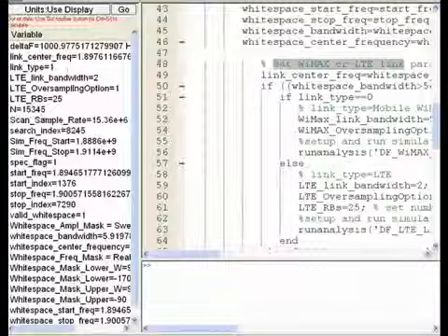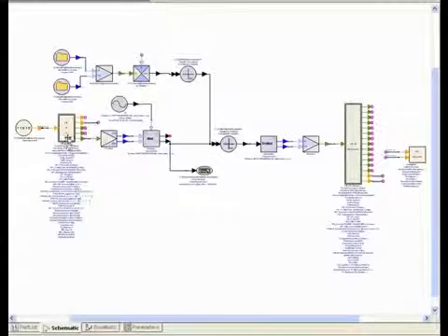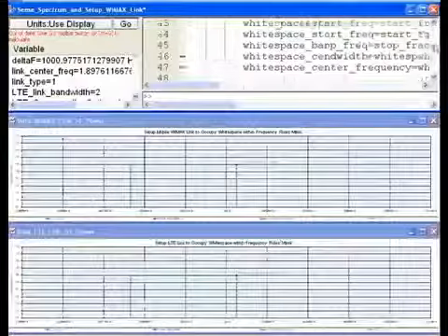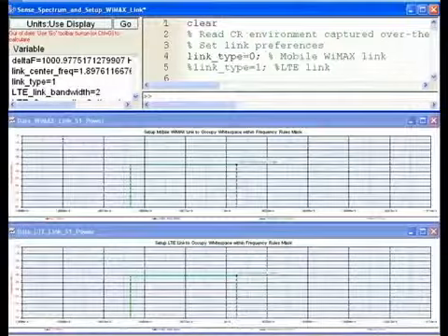Likewise, if we were running an LTE link analysis, we'd be setting up the center frequency on an LTE downlink source, which is an OFDMA signal. And again, to this, we're adding the cognitive radio environment that has been stored out in these ASCII files. And then the composite signals run into an LTE receiver, which performs baseband post-processing to enable the coded bit error rate simulation to be performed on the link. So that's a real quick overview of the demo setup. Let's go ahead and do the live demo.